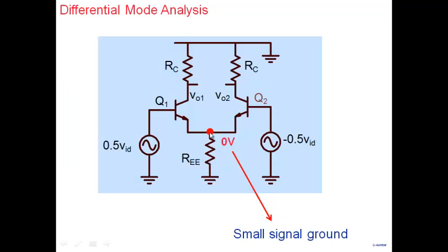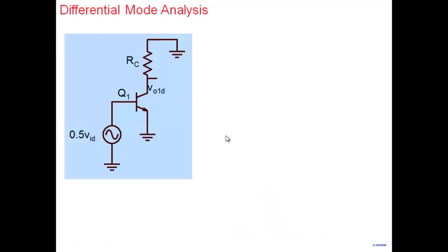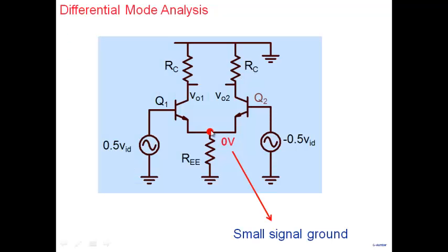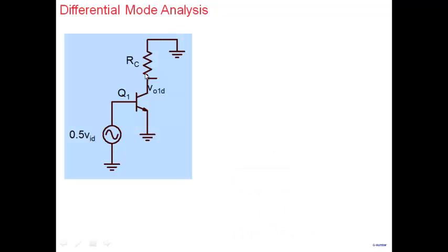And then note, the two circuits separate out. So this point becomes ground and this point becomes ground here. So it becomes like this here. That's what the circuit becomes. Left half circuit becomes here. Right half circuit becomes exactly the same here. This point is ground. Okay, so the two halves separate out. And this now looks like a normal common emitter amplifier.